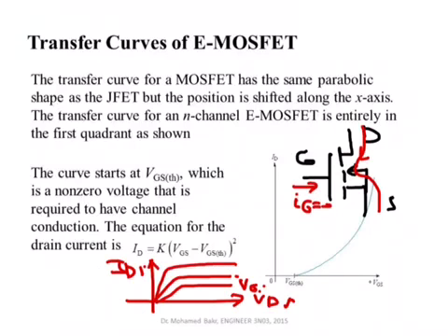I want you to understand very well that the current is really a function of VGS and VDS as well. But the formula given in Floyd assumes that we are in the region we use most of the time, that we already passed the linear region where IDS was a linear function of VDS, and now we are in the region where it depends only on VGS. You can see when you change VGS from VGS1 to VGS2 to VGS3, the current will change, and the change is quadratic. So keep this in mind.